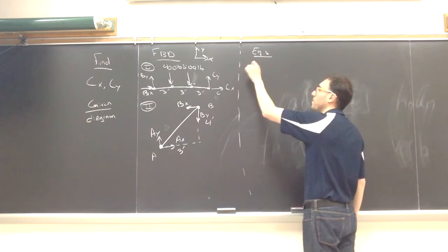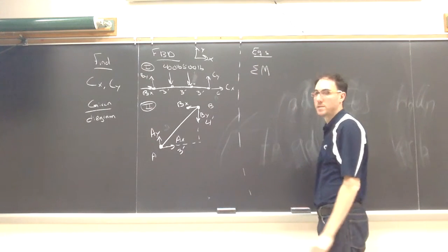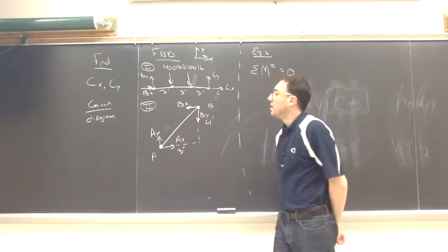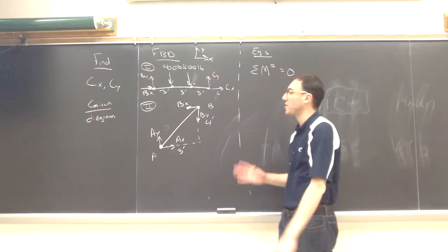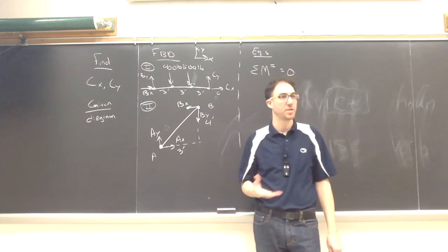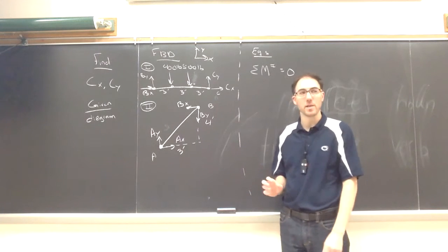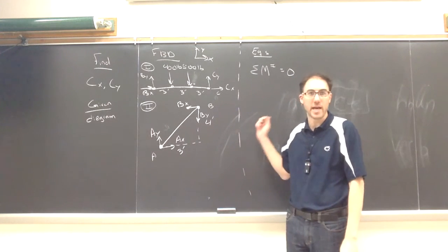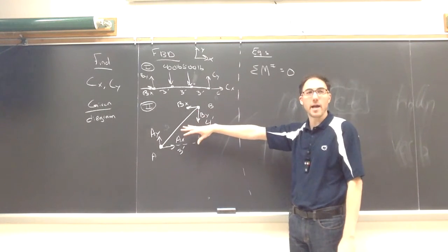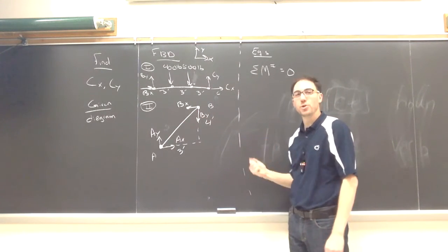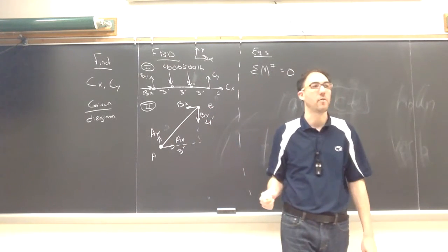So I'll just start with picture 1. Actually, I will start by summing the moments in picture 1. Like before, it doesn't actually matter where you sum the moments about. You'll still be able to get the right equations, but solving it by hand, you can make your life a little bit easier if you take this rule of thumb into account. On any free body diagram where you're summing moments, it's usually better to sum the moments about a point that only occurs in a single diagram.